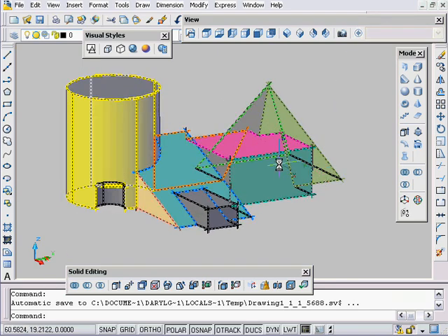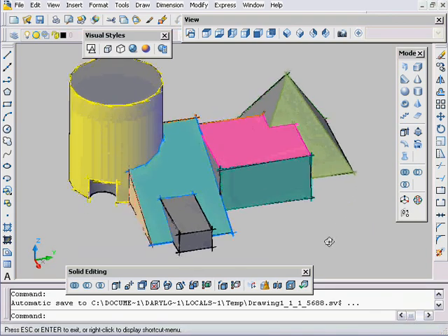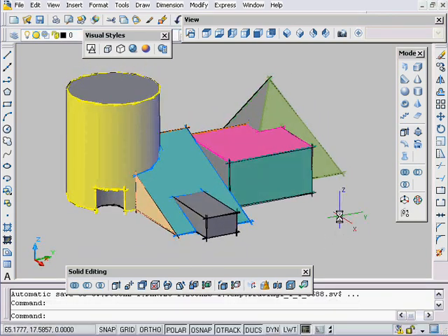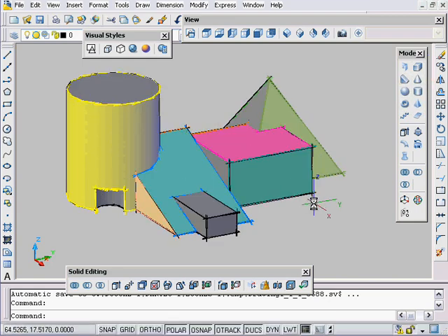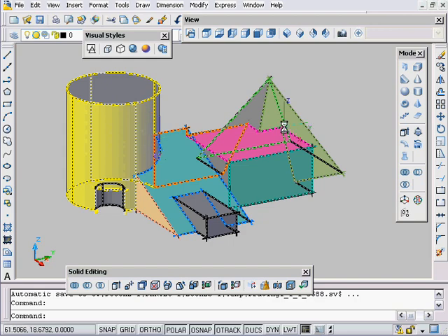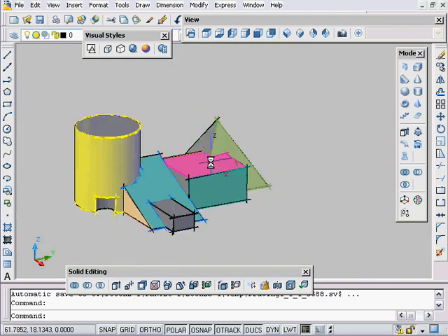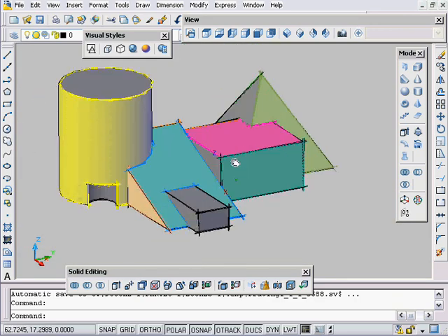And just before I get to that, I just want to show you what I've done in here, to get us up to speed and give us a little something to work with. All I've done here really is used my modeling tools, using the box and the wedge and the cone and the cylinder, etc. Created some very basic shapes. And then I used my union to union all of these together, which then gives me my seam lines in between and around this edge.